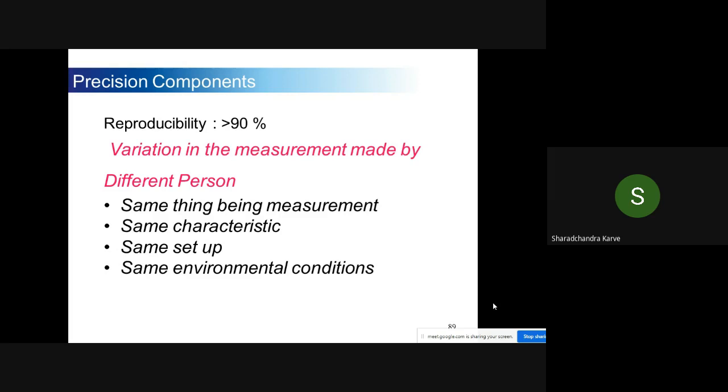Okay, and you must ensure that what is being indicated, that I have used 1000 kg or 1000 tons of raw material, is authentic and has been validated by a flow meter, and the flow meter is regularly calibrated, so that I trust that whatever yield I am calculating is right. That is the idea. The next part of this: one is accuracy, other is precision, and the third part is, next slide, please.